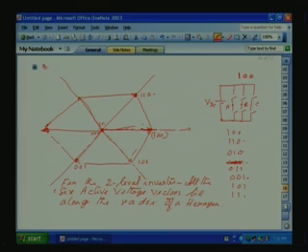With these combinations, how do you get an average variation of the voltage space vector for which the tip traces a circle with a uniform velocity? So, in this hexagon we can have different circles with a different average variation. This is one circle, this is one circle.